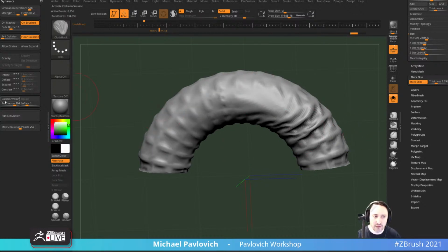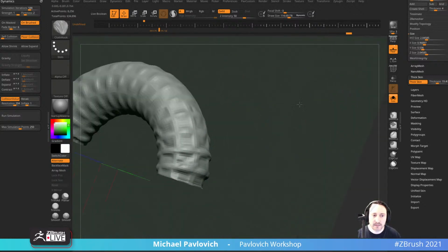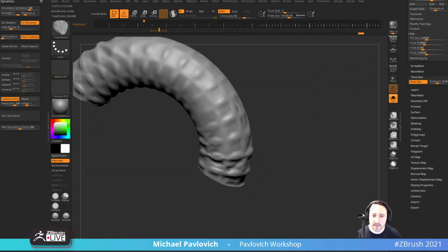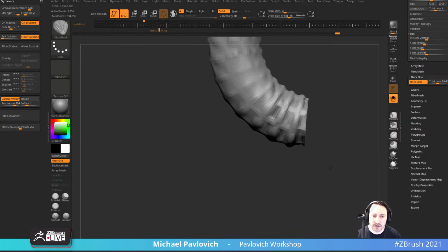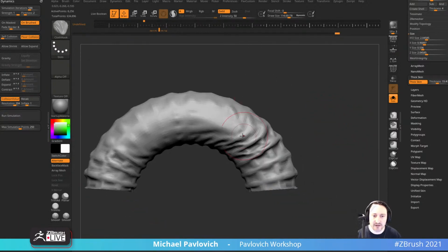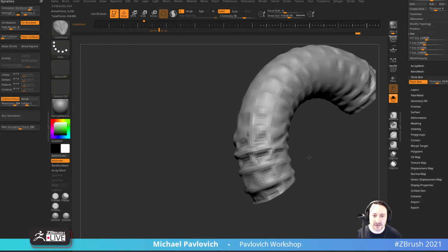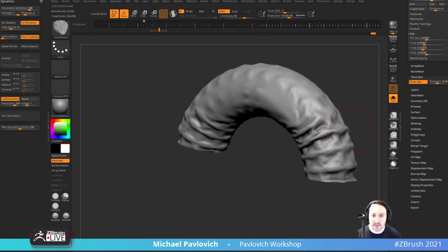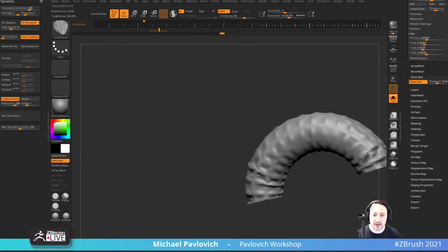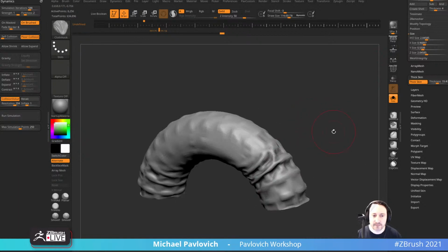Now, if you do want to keep that on, I don't think it's going to hurt you at all, and that'll ensure that that underlying mesh here, let's go turn that floor off, is still colliding appropriately. But if you ever get in a weird position where this collision volume's kind of in your way, thick skin should probably be good enough. But anyway, that's how you can put a cloth over a metal tube there.